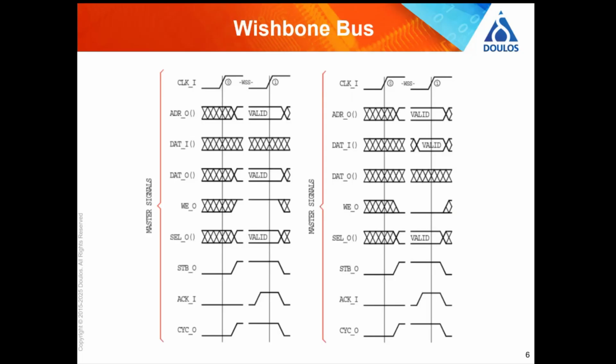And it sits on this thing called the wishbone bus, which is quite a powerful bus. It's got all the usual signals that you expect to see, address, data, and so on, and then lots of control signals, and you can have multiple masters as well as multiple slaves. So it's a proper big, powerful bus, and that will become relevant at some point today.